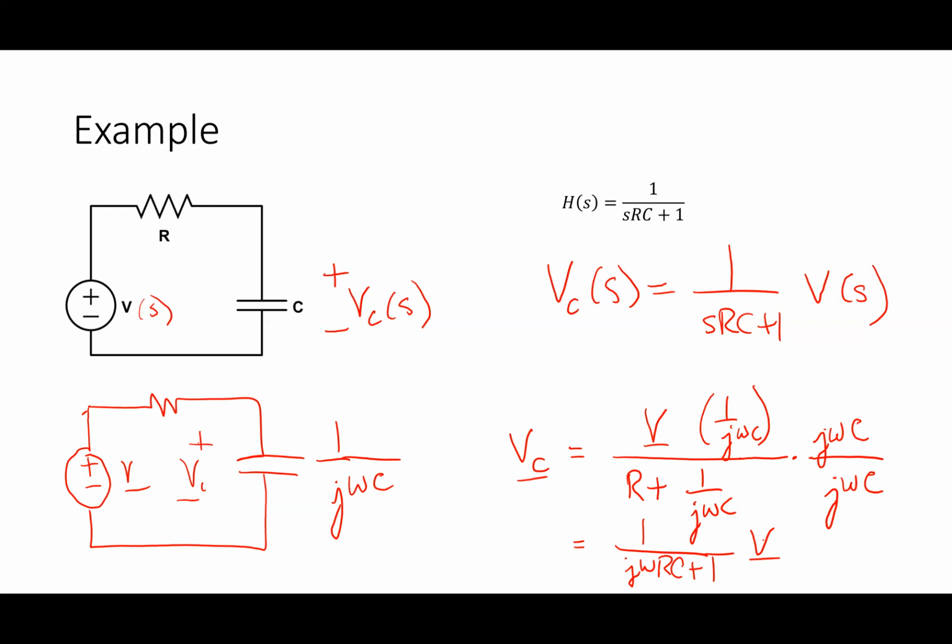Now there's a reason why we do this. I like looking at this stuff as a function of S because it allows me to start thinking about something called filters, where I think about a circuit and I say, well, what happens if I put in an input that has a particular frequency? What happens at the output? Does it get bigger or does it get smaller? Or is it the same? So that's what the Laplace is used for, to analyze the output of a circuit.